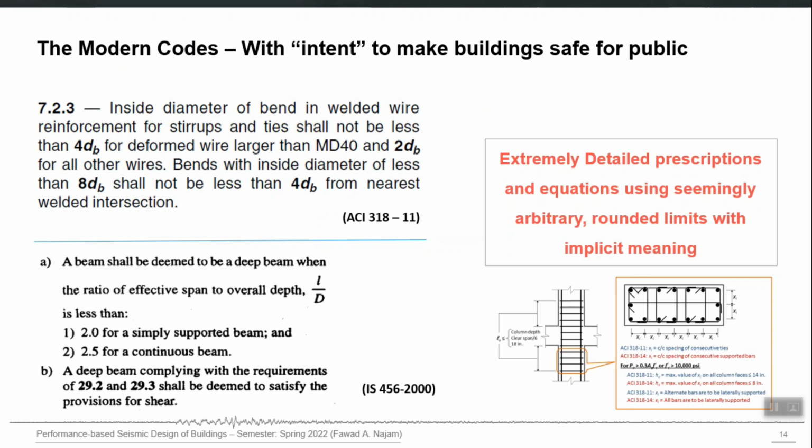and then the analysis results can be converted into other forms of damage. For example, if a certain beam is cracked, you can directly calculate what repair cost can be expected to repair that cracking. Or if a particular column or a shear wall gets yielded, you can convert that information into repair cost. There are models available which can convert structural responses into casualties, into number of injuries or deaths or downtime, into repair cost, right. So there are models available for that.